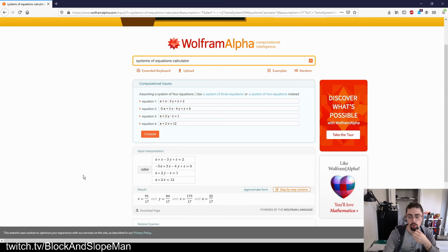And I'm not super upset if you use these. I think it's worthwhile to know how to solve these, but this is probably one of the easiest ways to do it. Setting up the loop equations properly is going to be the most important part, and then looking at this and making sure that your answers actually make sense. Those are important details. Essentially you're setting up the equations with every current, and then the batteries, the potentials that you know, on the equal side.